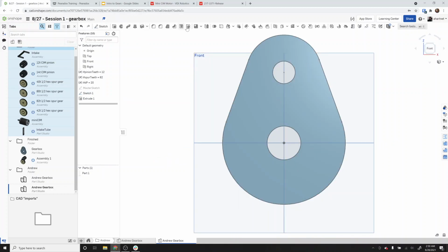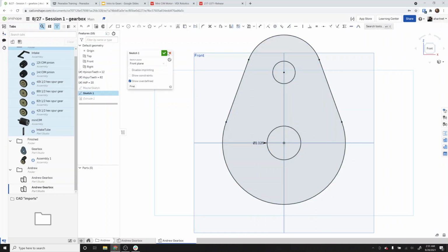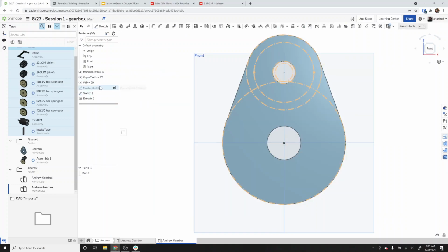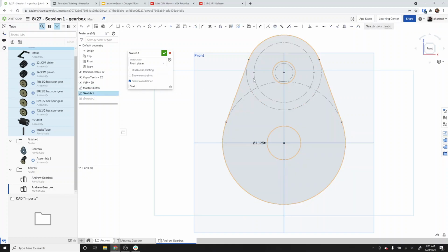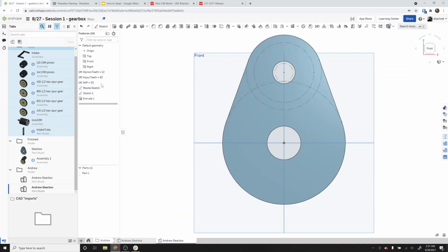And there's this hole tool. Let's go ahead and check and make sure this sketch is missing it. Let's unhide the master sketch as well. We want to use these 2 points here. So I'm going to select those two and hit U to use them. And then I'm going to hide the master sketch, and I'm going to use this hole tool.